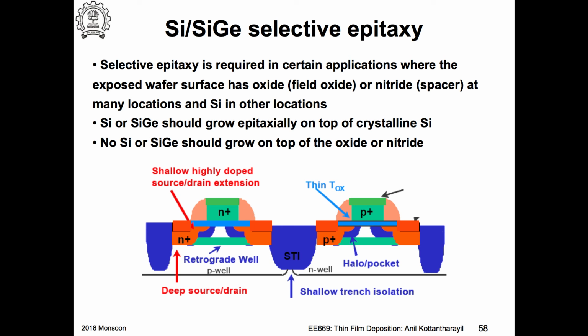So now I need to cover up this polysilicon because I don't want to grow anything. I need to cover up this device because I don't really want to grow anything here. Okay. So that is one example. So I'm going to cover up all these things, etch the source drain, okay, and when I actually make the transistor with a gate, I'm going to use an oxide on top of polysilicon.